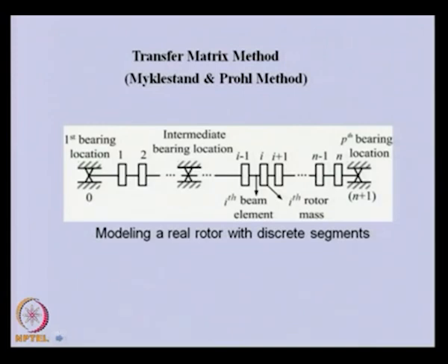So, let us take a multi-mass rotor system in which we can have multiple supports also, and in this we have labeled various stations from 0, 1 up to n plus 1. All the important disc and bearing locations need to be assigned some station number. For developing the point matrix or field matrix, we need to take out a representative beam segment or rotor segment, and from its free body diagram we will derive the field matrix and point matrix for these segments.